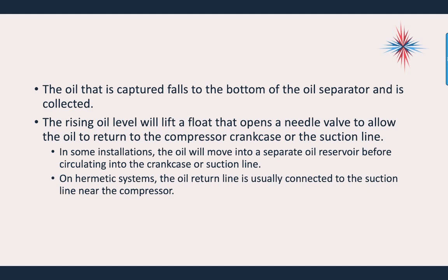The rising oil level will lift a float, almost like, for lack of better terms, a toilet tank float, that opens a needle valve to allow the oil to return to the compressor crankcase or the suction line. In some installations, the oil will move into a separate oil reservoir before circulating in the crankcase or suction line.